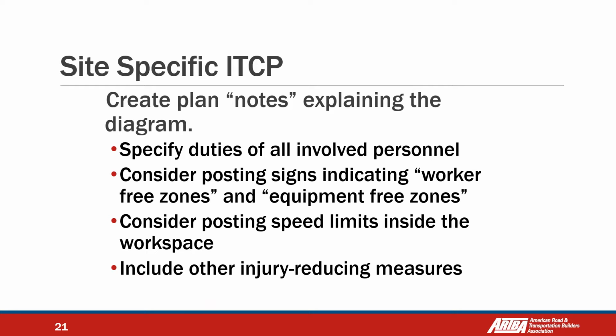So create plan notes explaining the diagram and specific duties of all involved personnel. Consider posting signs indicating worker-free zones and equipment-free zones. Remember also that you can use all the MUTCD signs and devices inside of the work zone too, to improve the traffic. There is no prohibition on using temporary traffic control devices inside of the work zone, so we can use these resources too.